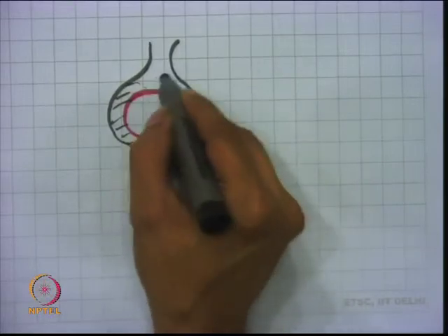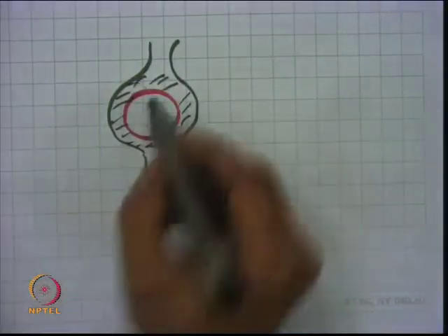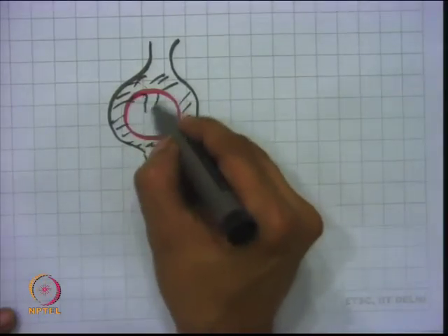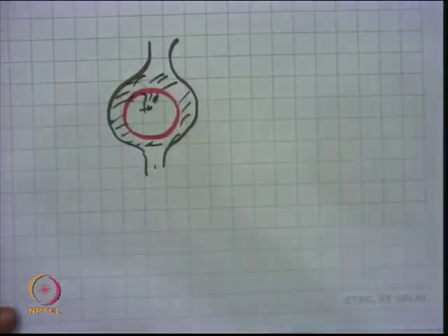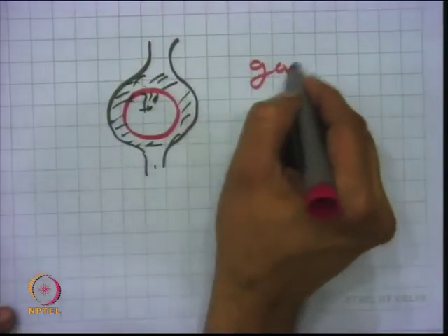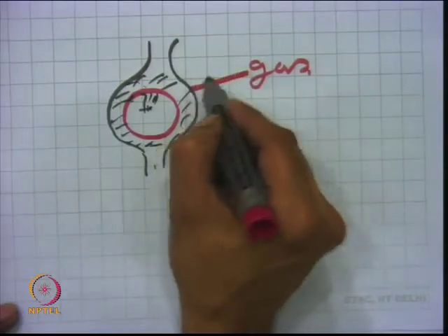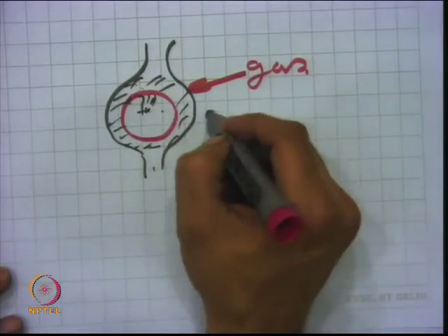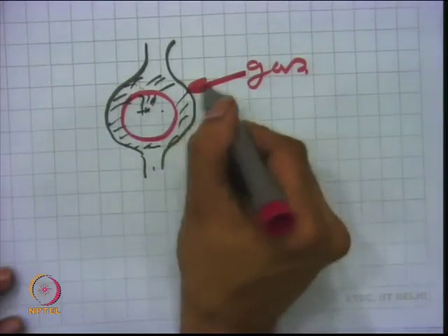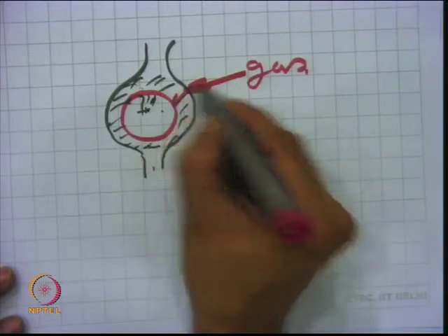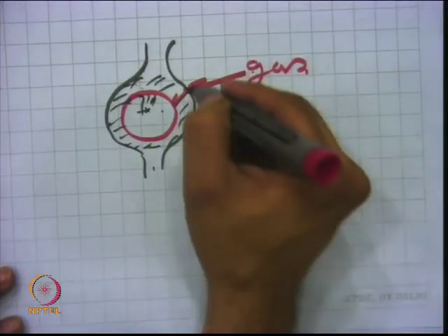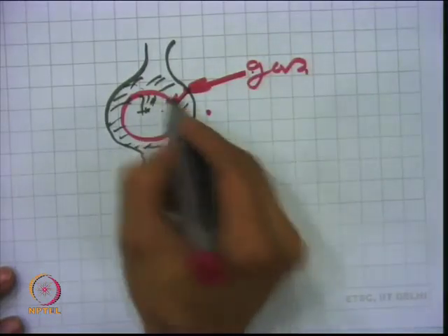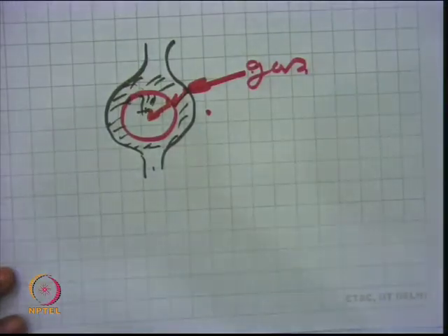So, there is a thin film of the liquid on the surface of the solid, and the pore of this catalyst is already saturated with liquid. Now when you have a gas, it will be somewhere here, and this gas is diffusing through this liquid film, which is a bulk of liquid surrounded by a solid. I will talk on that. So, here will be a kind of resistance. The gas has to penetrate this liquid film, come to the surface of the solid and then diffuse inside for the reaction.